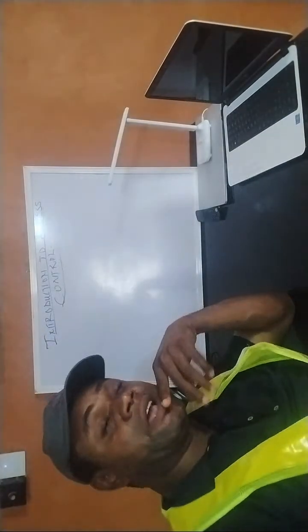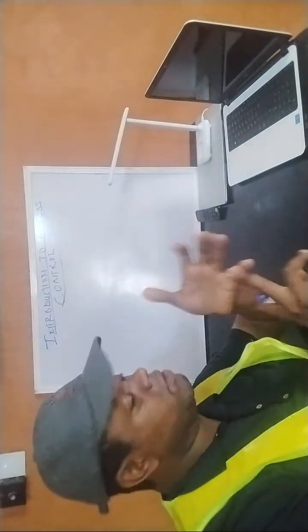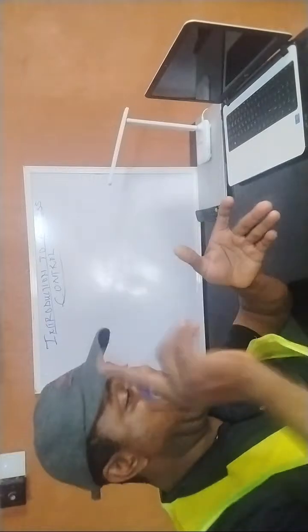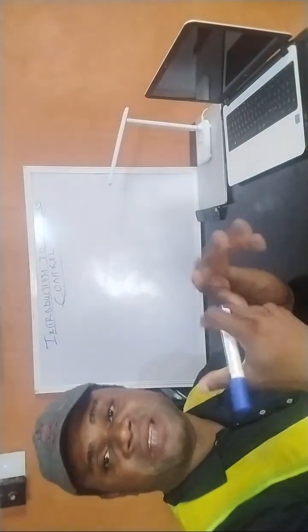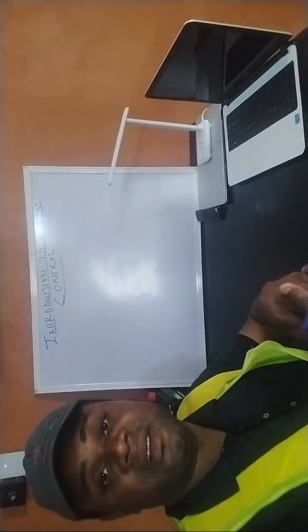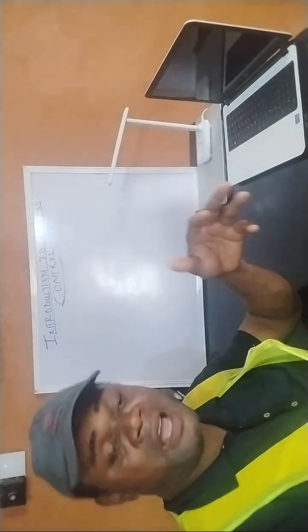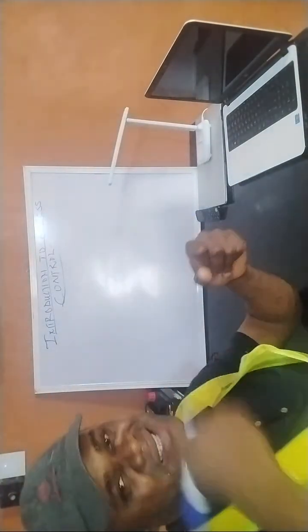Now you must understand that your lock, your power supply, and your push button are always inside the building. The only part you have outside, for somebody trying to gain access into that organization, is just the reader. Because if you have the password for the reader, or your biometric is there, you can access it. But the push button is always inside the building.